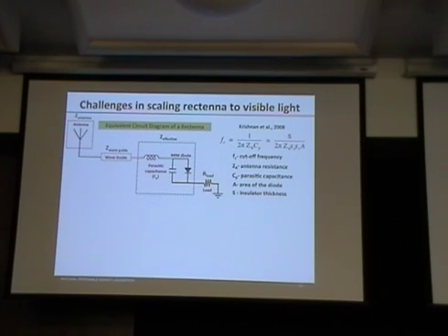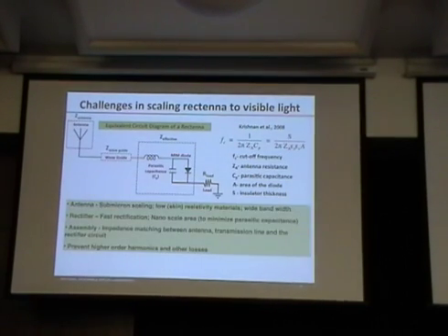So it's kind of cute because in some sense, this is a device that's all contact. There's nothing else. And the operational frequency is dependent upon this, so we need to basically minimize this capacitance. One of the things that we've been doing at NREL is looking at the design rules to essentially build one of these ultra-fast rectifiers. And to be honest, even if we can't get it to work at solar frequencies, so optical frequencies, there are a lot of interesting things that we can maybe think about doing with it, even in what would normally be considered the very, very far IR/terahertz regime.